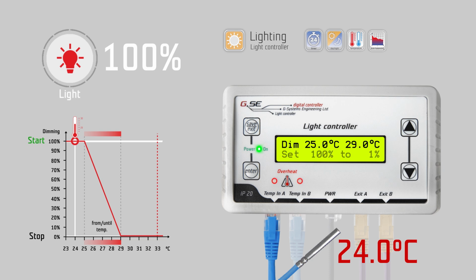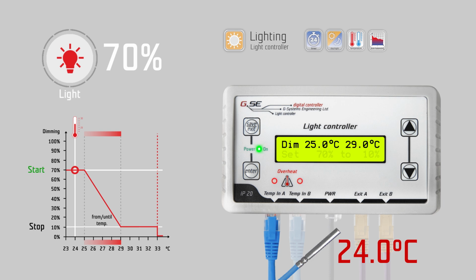Just below, you can set the dimming in percentage, according to the set temperature, which you applied before. Start dimming from 100%, which corresponds to the lower set temperature above. For example, we set dim from 70% to 10%. With the rising temperature in the room, the light dims to the minimum dimming value.